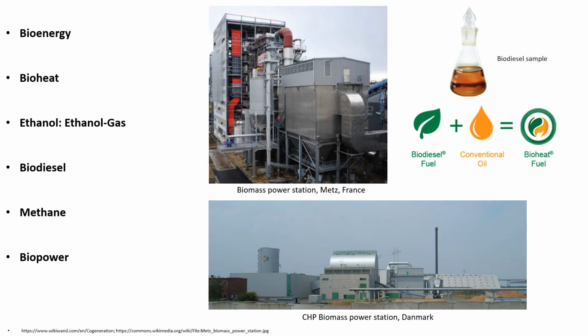Co-firing is employed to reduce emissions, especially sulfur dioxide emissions. It involves bioenergy feedstocks as a supplementary energy resource in high-efficiency boilers to produce electricity. Pyrolysis is thermal decomposition of biomass at an elevated temperature in an inert atmosphere or absence of oxygen to produce gaseous or liquid fuel. A small modular system generates electricity at a capacity of 5 megawatts or less for use at a small town level or at consumer level.